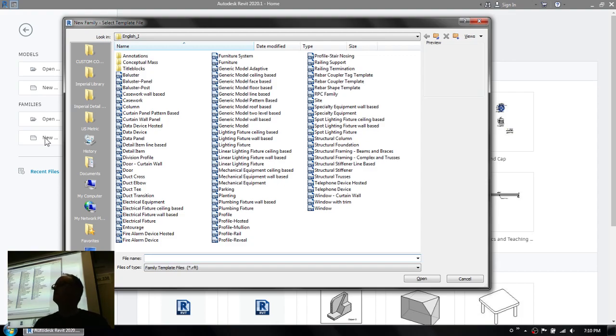So that means if you have a weird situation, you have to create the family from the beginning. Is there any way to change the host for an existing family? Sure. The question is, what happens if you've committed and built a family and then you realize, oh shoot, I need to change the way that it's hosted.